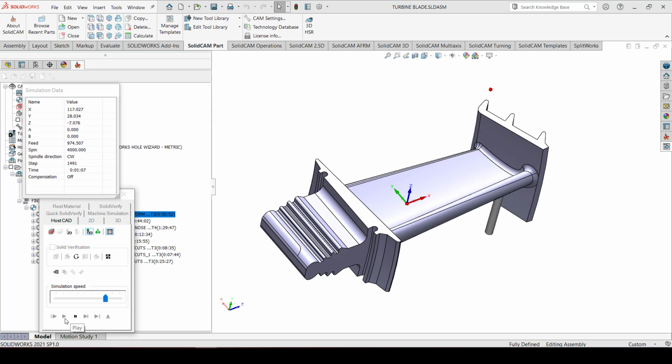So we use the bottom of the tool, and the advantage of going with a lens form tool is that you could give a bigger step over and yet achieve the same amount of scallop that you would get with a 16 dia ball nose using a very small step over.